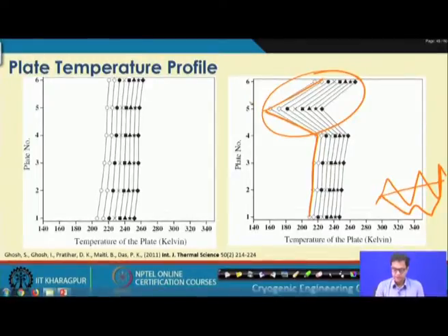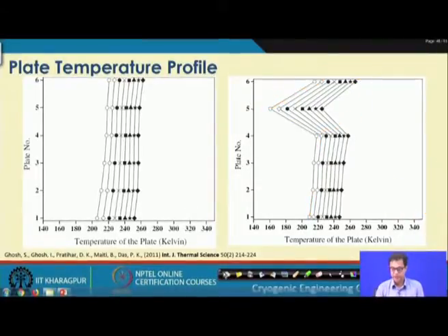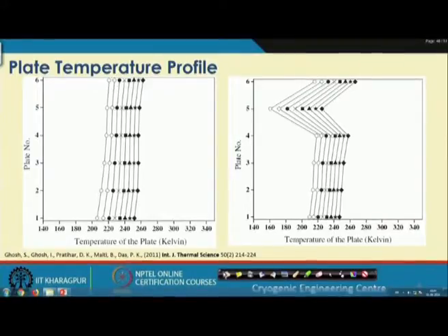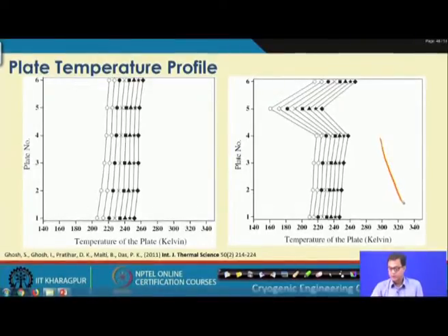So, these two conditions are criteria for the optimum stacking pattern: the plot of the cumulative heat load with the layer numbers, and, particularly in a multi-stream plate fin heat exchanger, the uniform plate temperature at a particular cross section at any location of the exchanger.